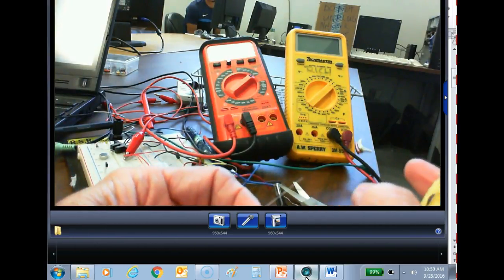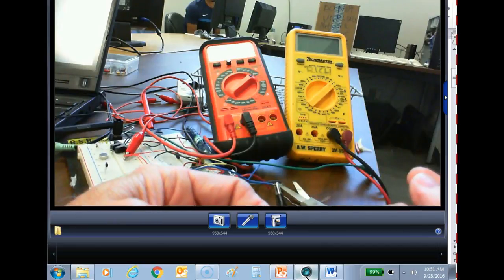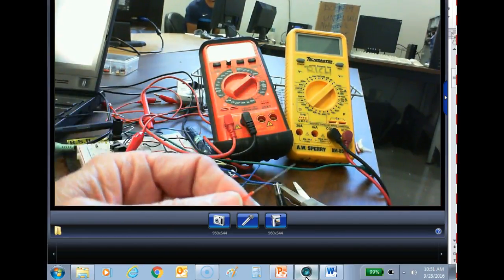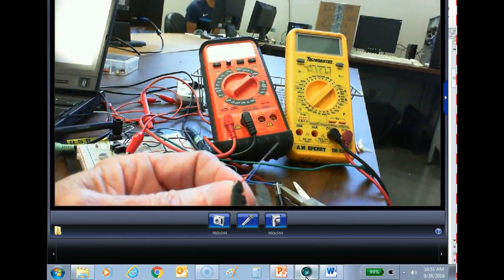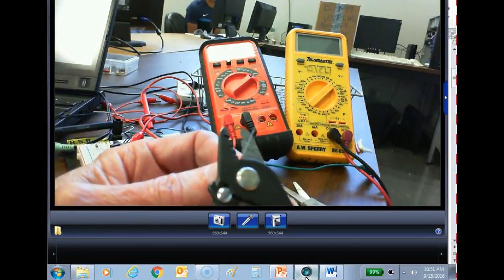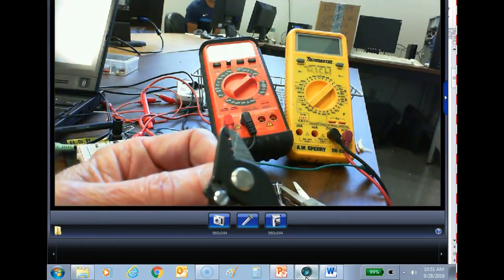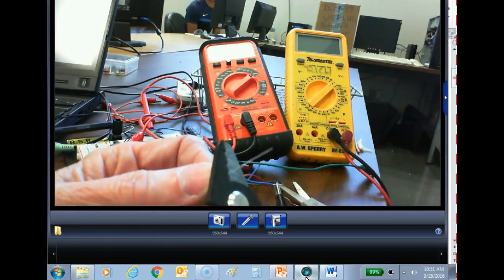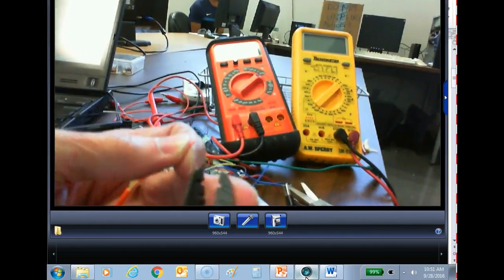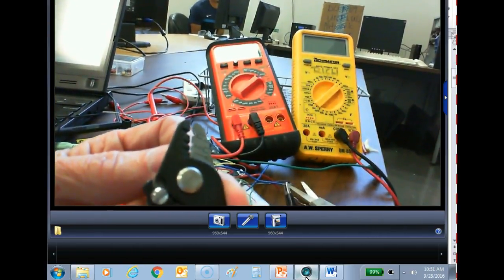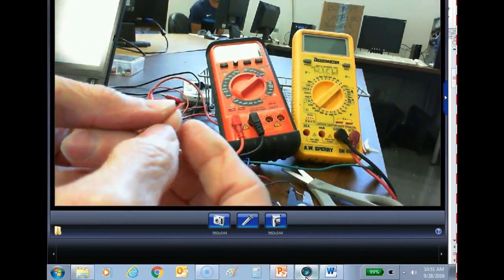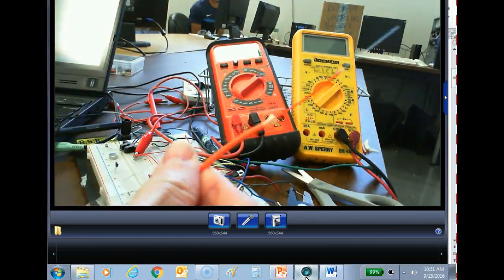Because guys, it's glass, and we've exposed this glass now, right? It won't focus in, but you can see the coating on there, the buffer coating. Be careful, we set it in that little groove, because if you don't, this will cut it. It might take a couple of strokes to get all the buffer coating off there. Okay. We're not going to touch the fiber now.